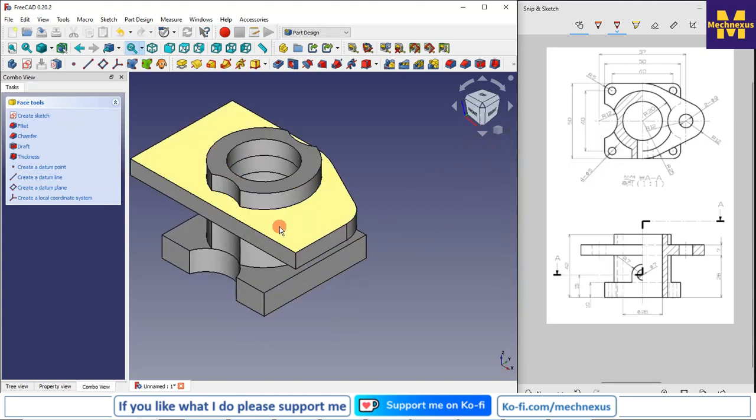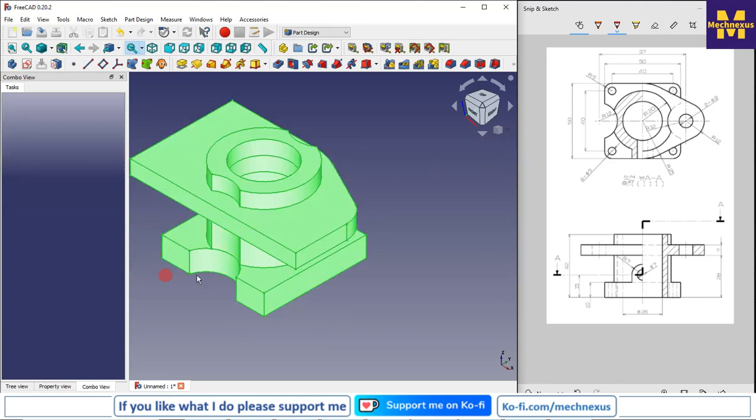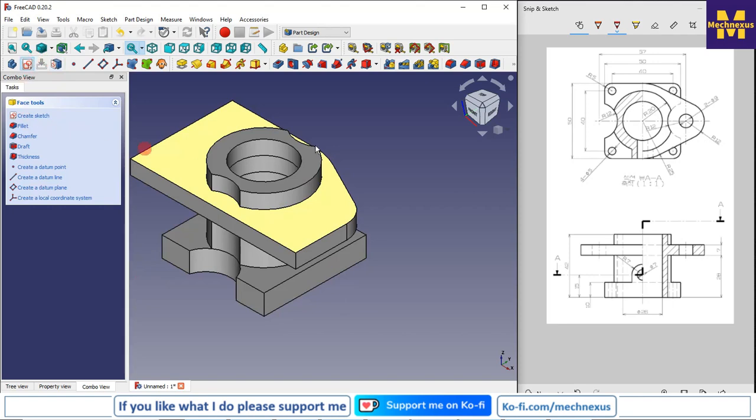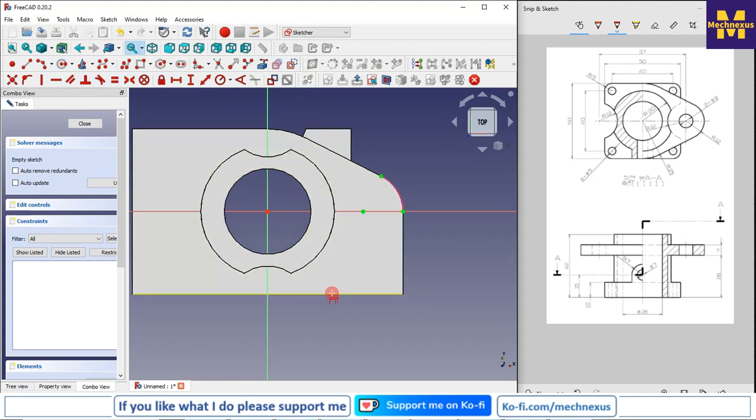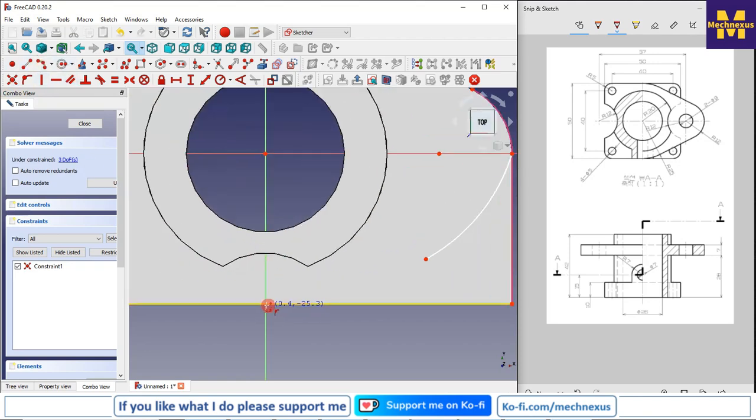Now we will do the same procedure on the other side and then we will mirror it. So I will select this face, create a sketch, and now it will be easier for us to draw on the other side. I will project this arc, project this one and this one. Now I will select a 3-point arc, and from here I will select arc.